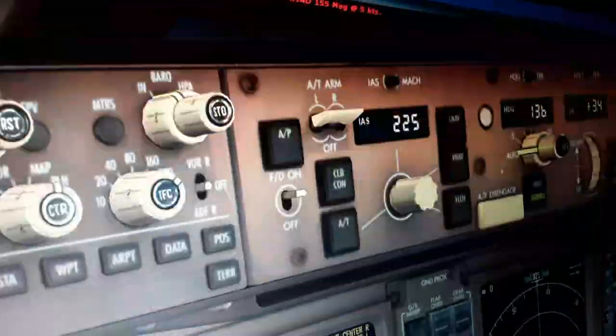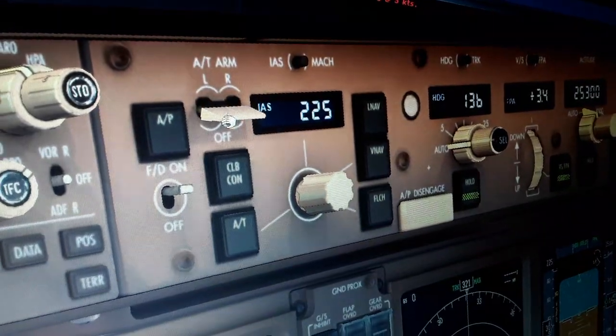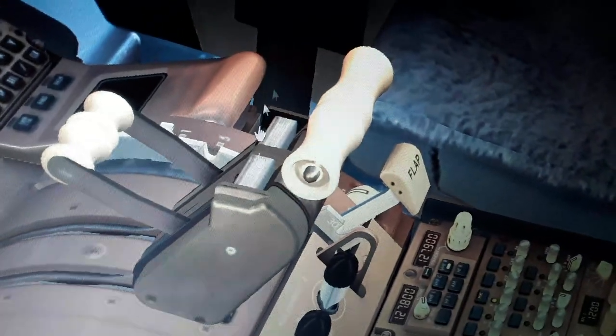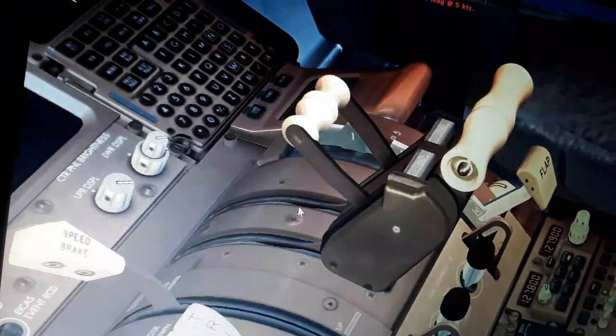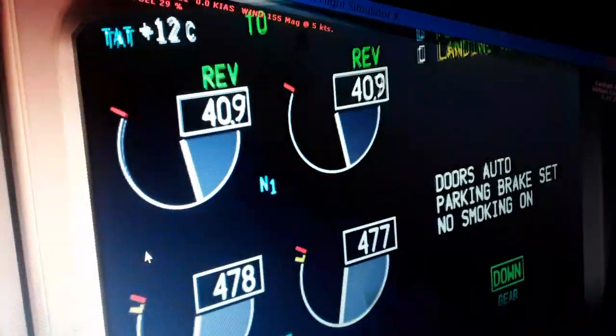So you can see this is controlled mainly by the flight director and the auto throttle system for automatic thrust arrangement. If you want manual thrust, you disengage the auto throttle using these switches over here on this side of the controllers of the thrust levers. So we have the takeoff go-around switch, and we have the thrust reverse. You can move this up, and we have the thrust reverse slowing down the aircraft on the ground after landing.